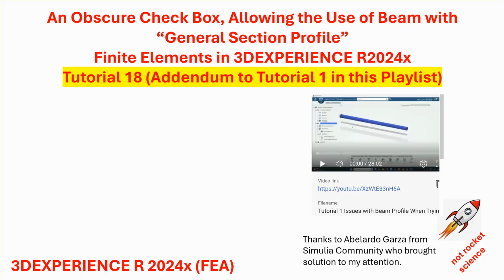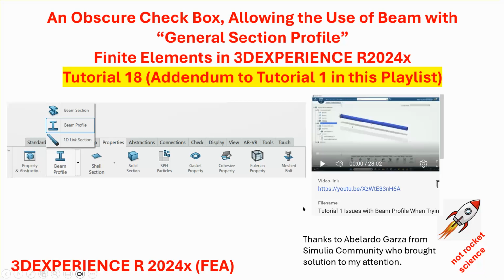There, I mentioned that there are some issues with the beam with a general section profile, okay? And it's not working. So anyway, let me go ahead and explain what the issue is. When you do beams, you can obviously specify the profile by this icon. That's what you have to do first. You can make it rectangular, circular, trapezoidal, etc.